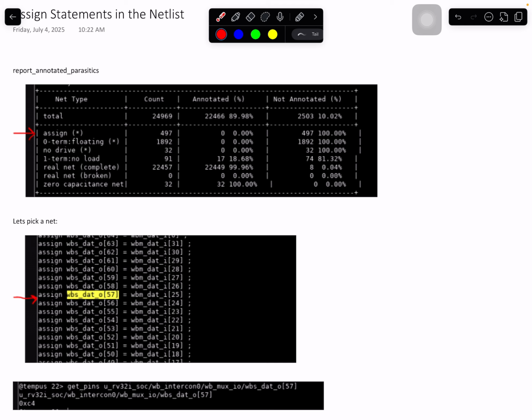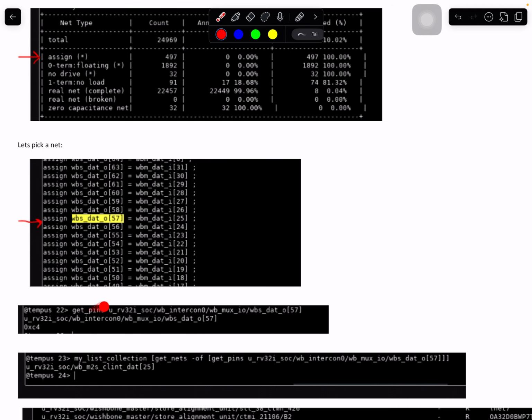All right, then inside Tempest I tracked that, and I wanted to get this pin of a module. Wherever this is, you can search back and look at the module definition, search for the instance of that, and then try to find that instance within your design with get_pins or get_cells hierarchical. I did it differently.